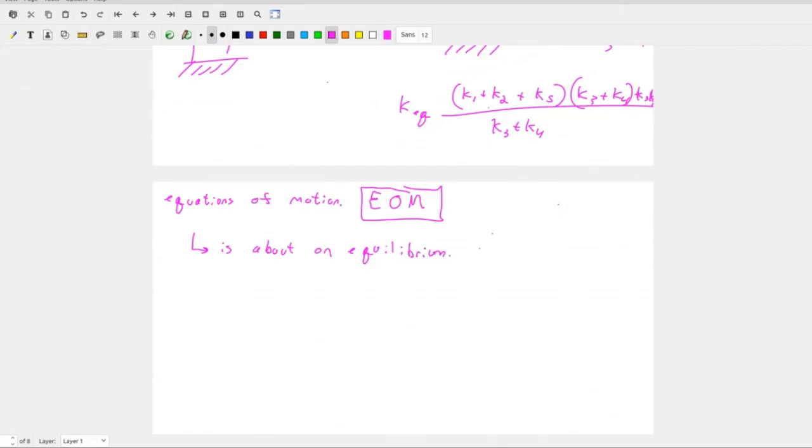And for the homework example we did, that's why we had to solve for our delta deflection, because we have to find that equilibrium point. Does that make sense? It's a transfer of potential energy from the spring to the kinetic energy of the mass. You always have the same amount of energy, at least if you don't have a damper, and it's just going to sit there and vibrate forever.